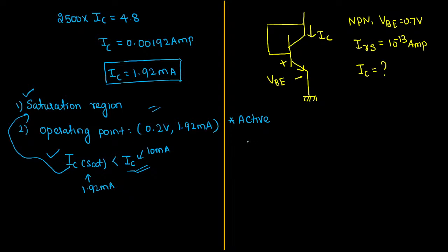And the second thing is, when the transistor is in active region, how will you write down the expression for emitter current? Sir, emitter current IE can be written as, not approximately, exactly (1 plus beta) times the base current IB. And collector current IC can be written as beta times IB. Undoubtedly, this is correct, sir. But they haven't given any data. Beta value is not given. If beta is not given, then how will you calculate?